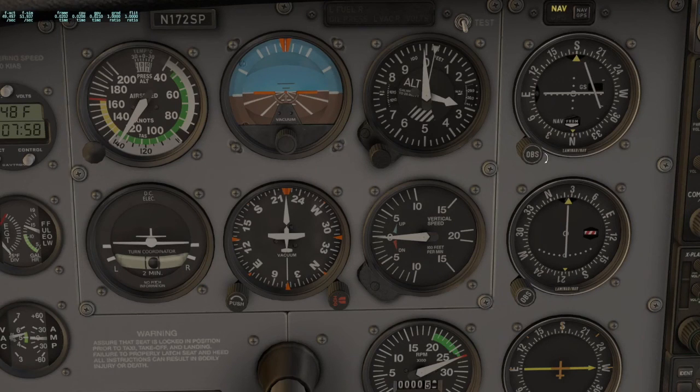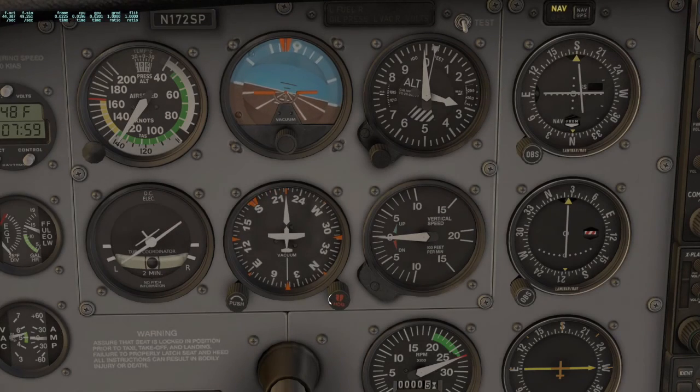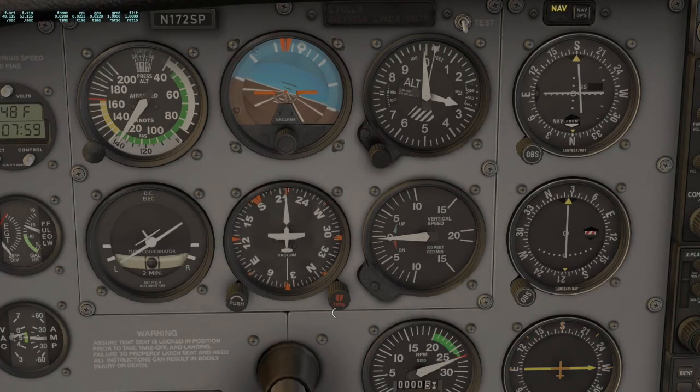Here we go. Now the needle is starting to move. We are about to intercept. We're getting very close to the 180 radial, and then when I get close to it, I'm going to start turning to head in that direction because I'm going outbound, meaning in the 180 in the south direction. If it was inbound, I would have turned in the opposite direction, which is north. Okay, so it's turning now. I'm going to start turning here south very slowly.